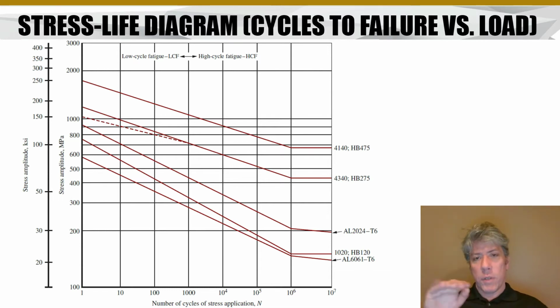All of them eventually exhibit this infinite life phenomenon, but aluminum does not. There's 2 aluminums on here, 2024 and 6061. Aluminum does last longer. As you go out, it's less sensitive to stress. You can get more and more cycles out of it, but there's no such thing as infinite fatigue life in